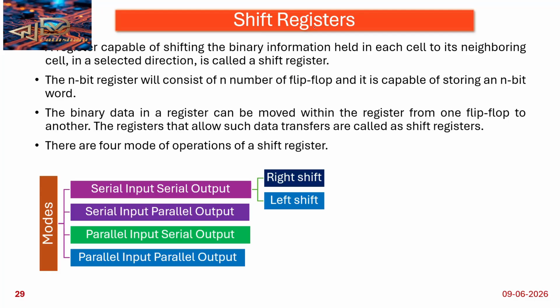And now today we will discuss registers. So a group of flip-flops is called a register. Okay. So we see a flip-flop is a single bit storage device, right? Whatever flip-flop you are considering, that is a one bit storage device. So with these one bit storage devices you can form a register. So that means if you want an n bit register, how many flip-flops are needed? n flip-flops are required.